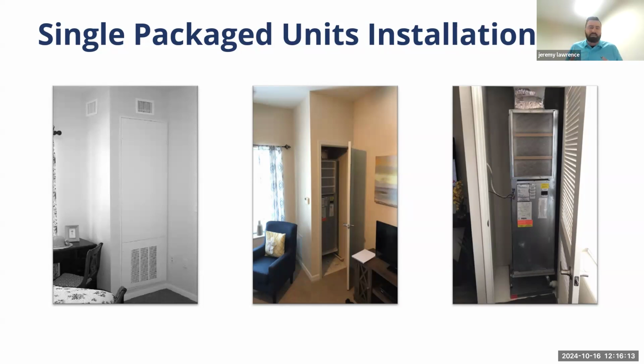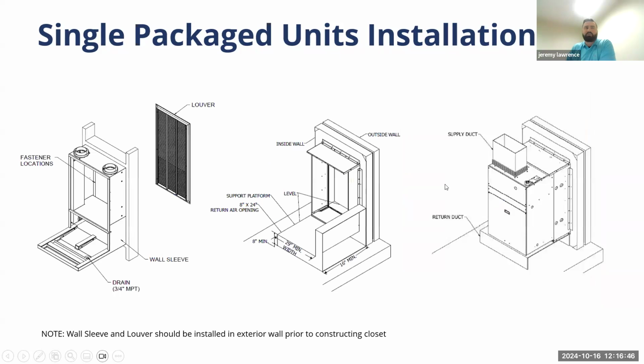And what that means is the sleeve that the unit sits in, the unit pushes directly into the sleeve, straight on. In a side install, you would have to put the unit up onto the sleeve, turn it, and then push it in sideways, which in the case of the third, this filter section would be facing right up against this wall. That's still okay. There is enough clearance to do that, but they can be harder to service because one side becomes less accessible on the far side. But yeah, the service clearances are quite tight for these units.